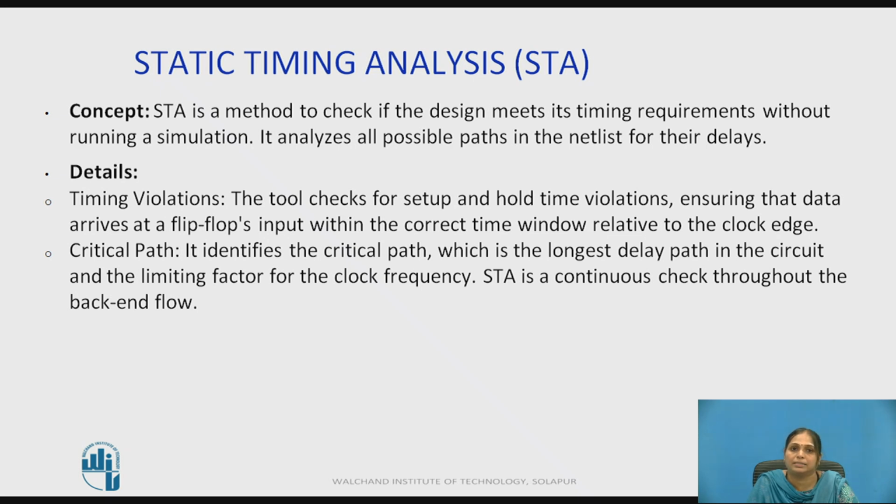Static timing analysis, STA, is a method to check if the design meets its timing requirements without running a simulation. It analyzes all possible paths in the netlist for their delays. The tool checks for setup and hold time violations, ensuring that the data arrives at the flip-flop's input within the correct time window relative to the clock edge.